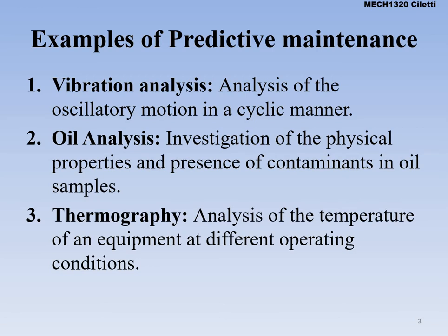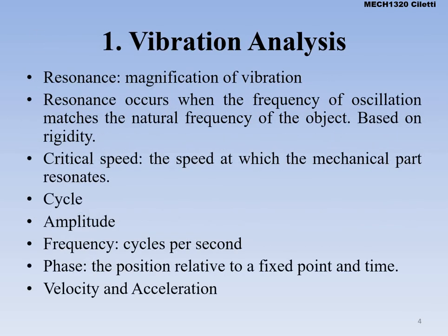We can also do thermography, so we can take a look at the temperature of equipment, all right? And we know what it should be operating at, certain temperatures versus what it shouldn't be. So we can see, all right, this is way hotter than it needs to be or where it's normally operating. Something's not working right here. So just being able to gauge and use different tools at your disposal to predict when something might break down. You can't foresee everything, but it's the idea of monitoring it to that baseline, okay?